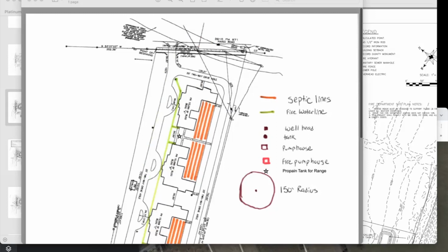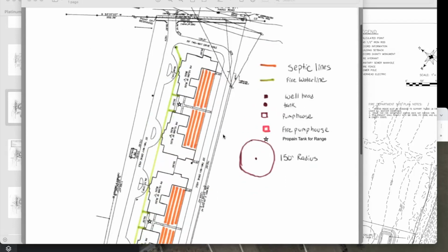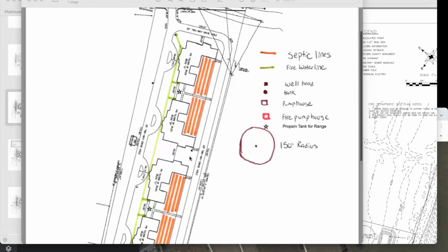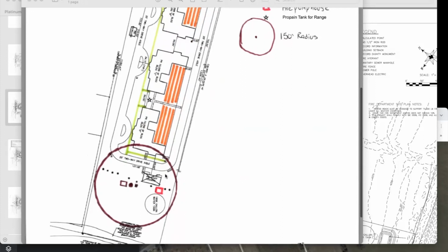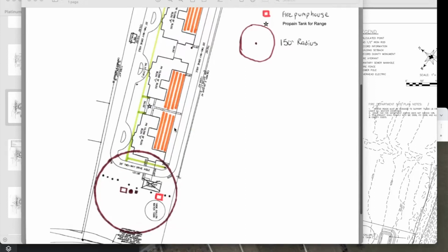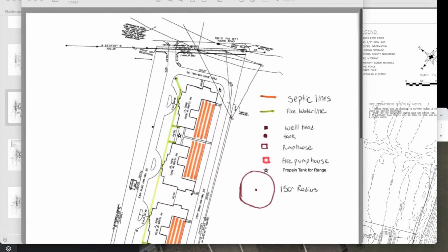This is where my power comes in, and there's a power pole here and one over here. Actually, this line cuts across over the house of where this would be, so this one we're bringing underground to come down here. We're going to set in a transformer over here so that we can run power to these 2 buildings, and then a transformer over here so we can run power to the well and the tank over here. And then probably one over here. And then this will just be sitting there waiting for phase 2 when I build these 2 buildings here.